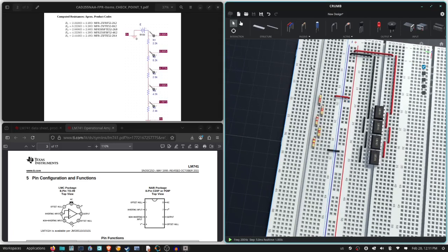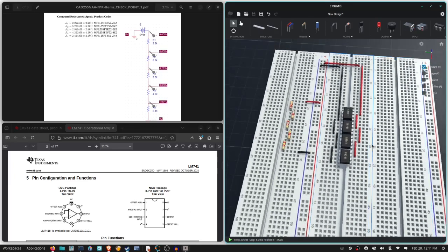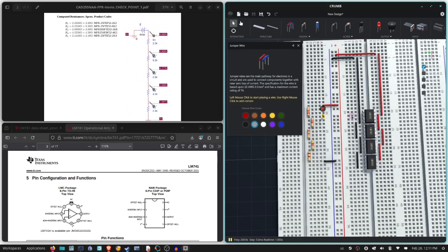So we're taking our voltage at each junction and we're sending it off to the inverting input on the operational amplifiers. So that'll be pin 2 for each. So this goes into pin 2 here. This goes into pin 2 here for our second. Here we're feeding our reference for our third. And then finally we're feeding our reference for our fourth op amp. Hopefully that makes sense so far.